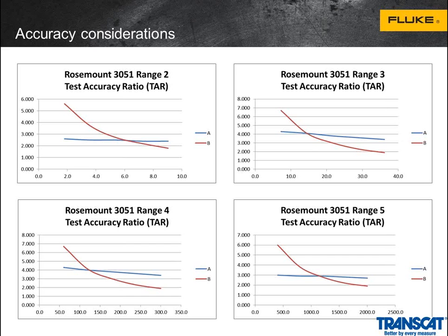So this is one of the key disadvantages of percent reading plus floor. While it gives you a great deal of accuracy at the low end of the range, it takes it away at the upper end. And so that's kind of the trade-off you have to make. As the transmitters themselves become more accurate and the calibrators are closer and closer to the line of good enough, what ends up happening is that this is starting to be something that an individual technician really needs to start asking his measurement staff and his design staff to say, look, the calibration tool that you are using really